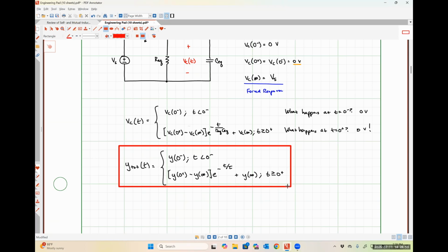Because in a natural response system, y at infinity is 0, so you're simply adding and subtracting 0. You'll waste a couple of seconds analyzing your circuit at t equal to infinity to find out everything was 0, and then you'll just go on about your day. You can use this relationship for every transient analysis problem in this class, and you'll be perfectly fine.